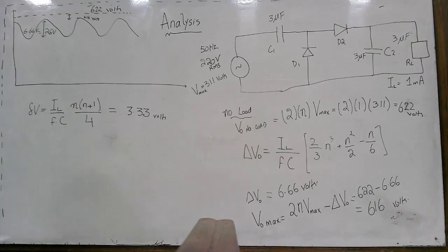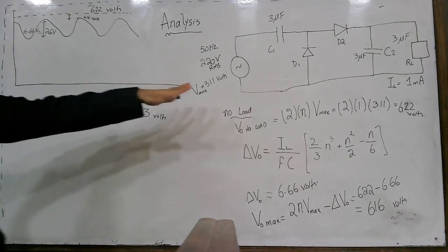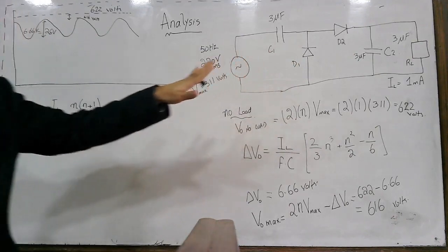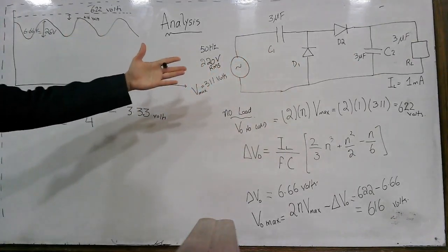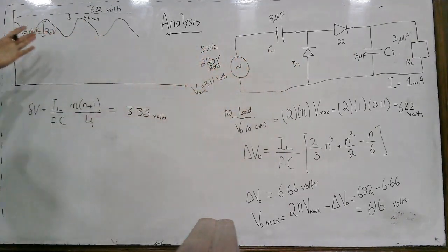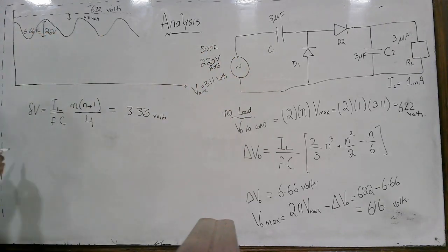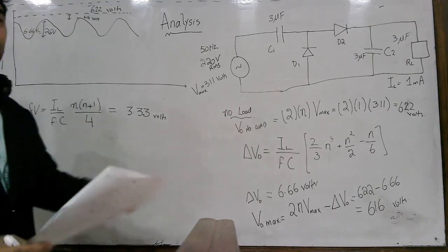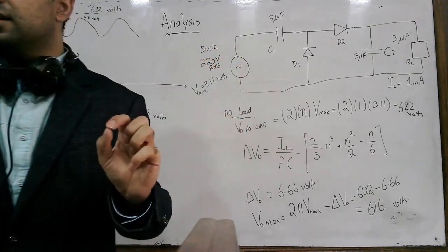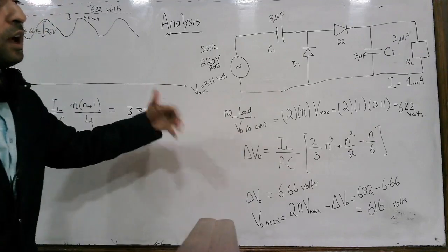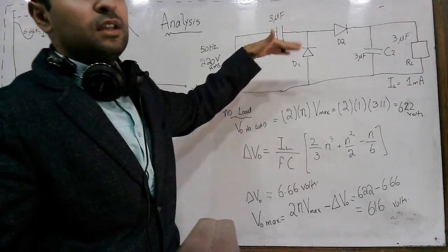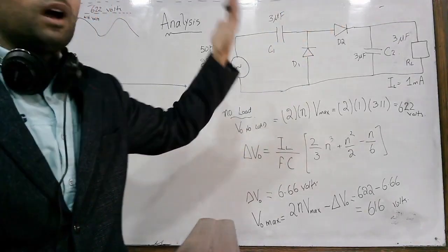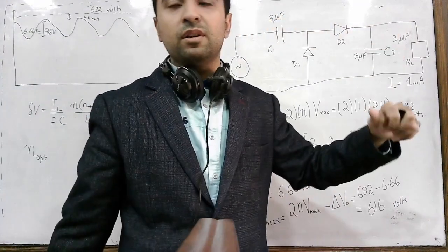So here we have analyzed what the output waveform of the single stage Cockcroft-Walton multiplier circuit should be. One more important step, as I told you, is the maximum number of stages. Once I have designed the single stage, I am interested in increasing the number of stages to increase the output voltage.